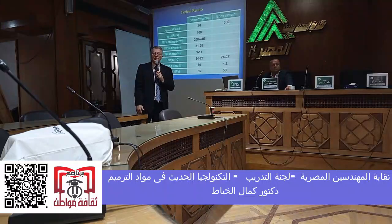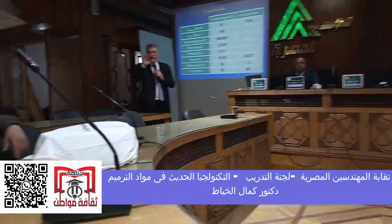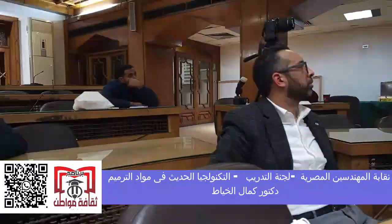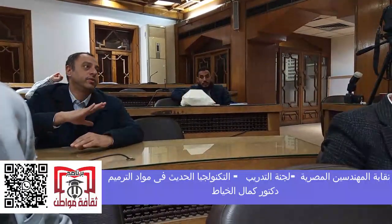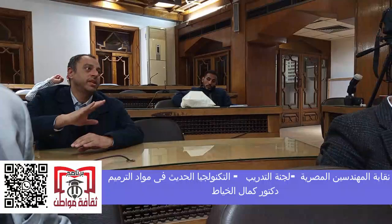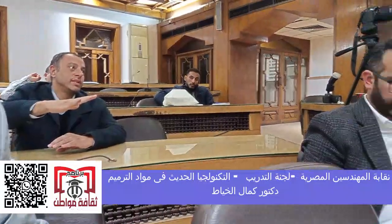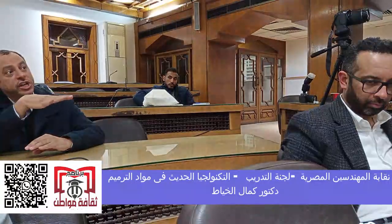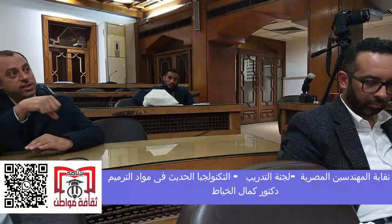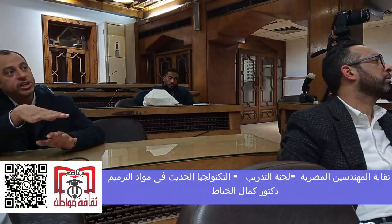I want to say that maybe the reason for these cracks is that there is no shrinkage reinforcement mesh. Oh, there isn't any. You're right. There's zero. No reinforcement. Zero. It is not good. It's just a concrete block. We have to put it in after 2 meters, or like this, 1 meter, 0.5. You're right. We have to put shrinkage mesh reinforcement. So in the first picture we see shrinkage cracks. Yes, this is the main reason: we didn't put shrinkage reinforcement.